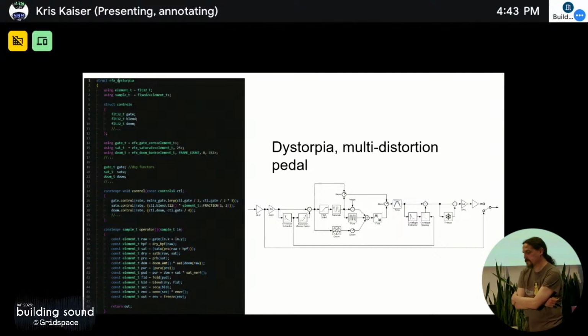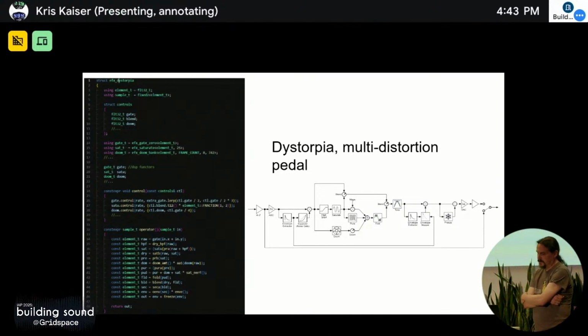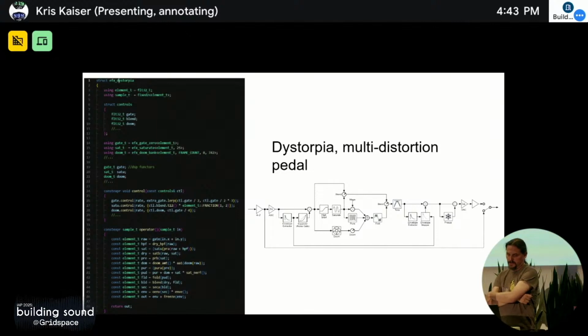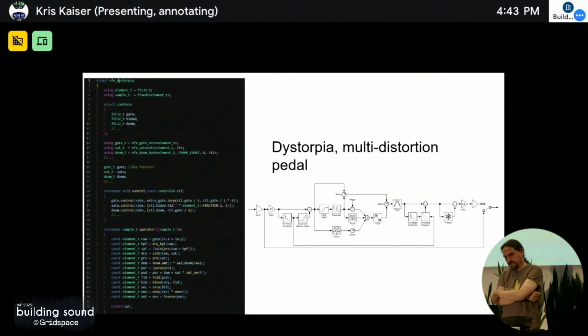We do all of our development in C++. That is what is on the left there. We do a rather functional style of C++. So the bottom left of that is the signal flow diagram, basically, but it is, as you can see, very, very simple and clean. We use functors a lot to essentially hide state from the actual signal flow, because inevitably when you're building these signal flows, they're complicated, they're hard to read, they're hard to debug, and so this is one of the coding techniques we use to make that better.